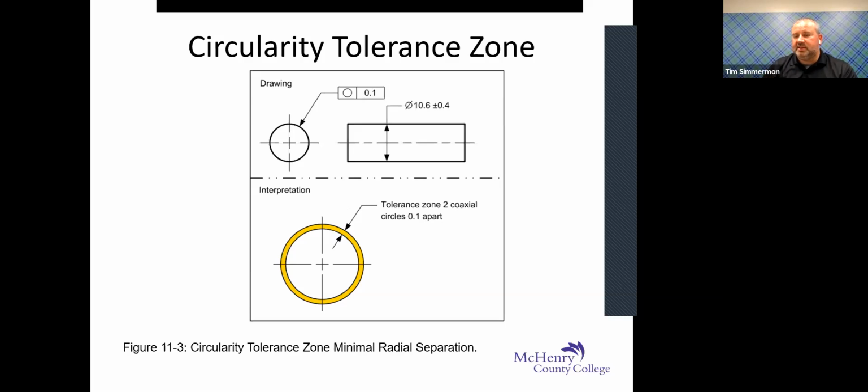It might be. It could be very sloppy for a pin that's going to hold your piston head to your, I forget the name of it, but the part that holds your piston together in your engine, but it might be super loose for the dowel pin that's going to be holding your Target nightstand together. So it's the application that is going to determine how tight those tolerances need to be.